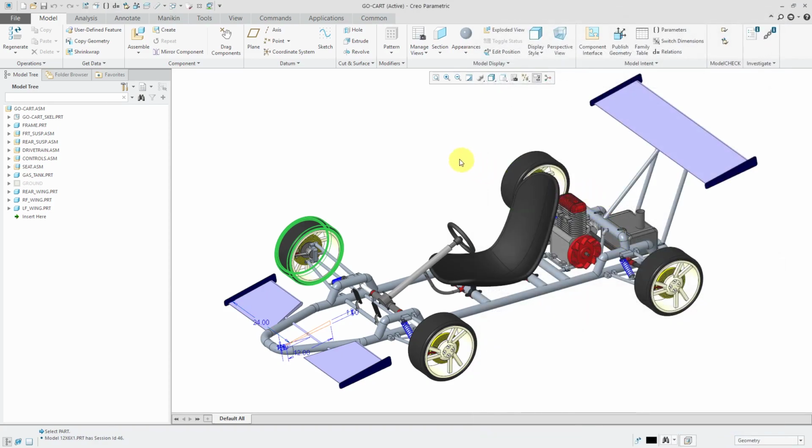I'm not actually going to write that relation. I mentioned in the slides that you can write relations at the component level in here. So for example, these have different component ID numbers, which is different than the session ID number. The session ID number is the same for different instances of the same object, but the component ID level really only applies to one level down in your model tree and is unique for the different components.